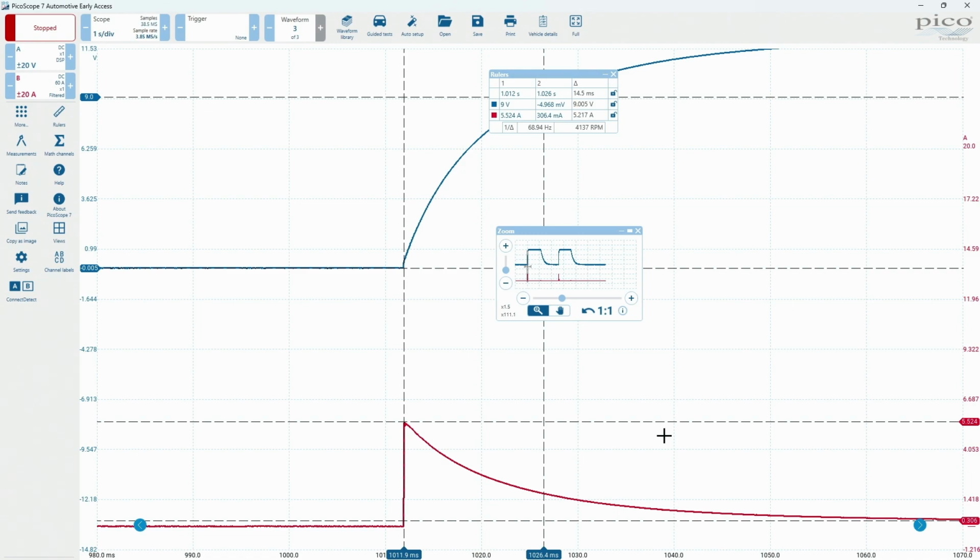So as this vehicle is keying up, we probably have the key turning on and the cluster's coming right to life really quick, but the PCM's kind of lagging behind. Not to mention all those other internal processors within the PCM. Some of them might be powered up by different circuits, that other power input that gets us 13 volts with no restriction in its current flow, so those capacitors and circuits and electronics inside can turn on immediately.